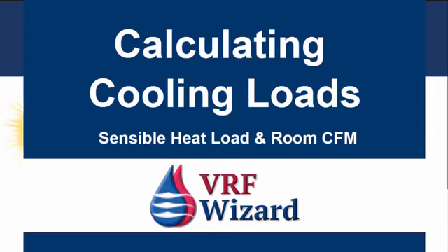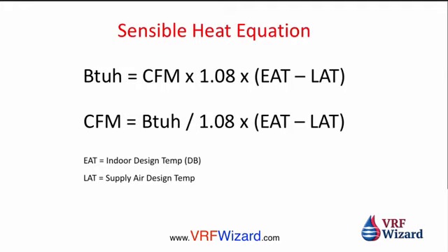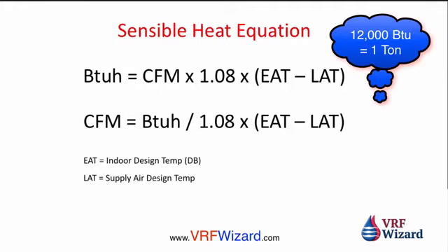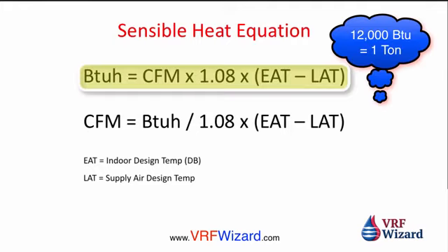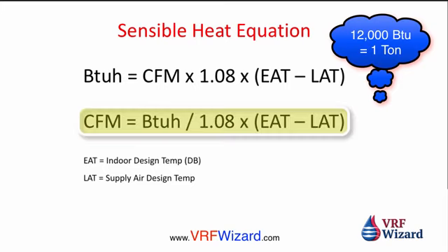We're going to cover how to calculate cooling loads. And then once you have your cooling load, you can figure out how much CFM is required. This is based on sensible heat. These are your sensible heat equations. So basically BTUs per hour we're going to figure out first. So from there we can determine on the second formula there how much CFM we're going to need for the